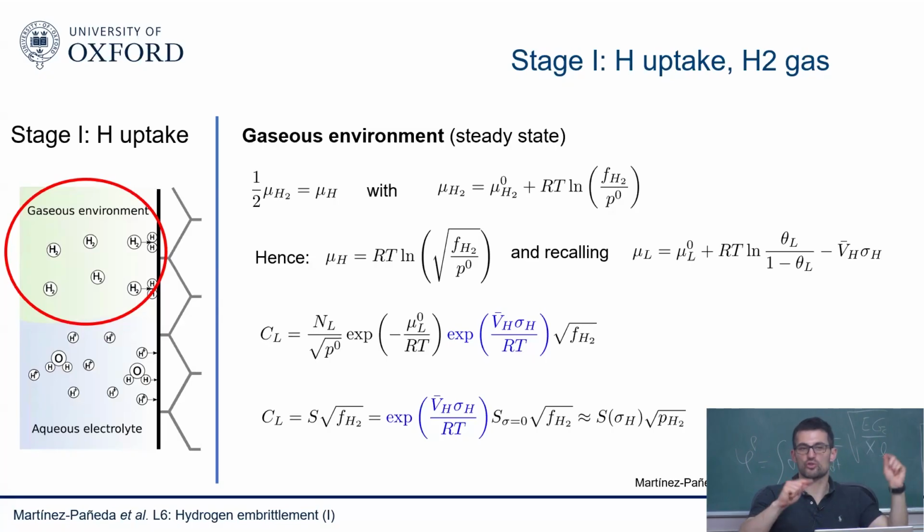That impurity, oxygen or whatever, will compete with the hydrogen atoms for the absorption sites in the surface and will prevent hydrogen from coming in. The Japanese, for example, are quite strong on this idea. This is something that you cannot measure at steady state, because at steady state your concentration of hydrogen in the metal will always be in equilibrium, so this surface phenomenon washes out.